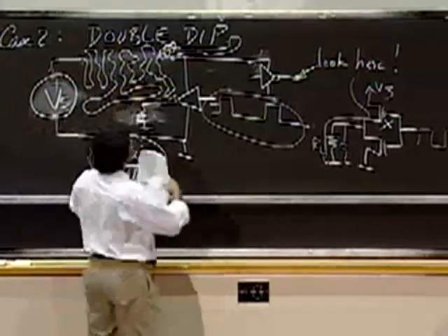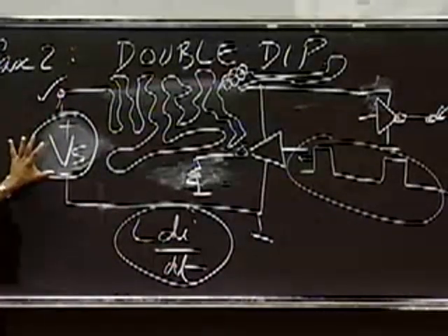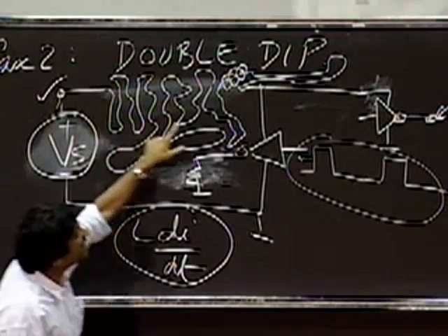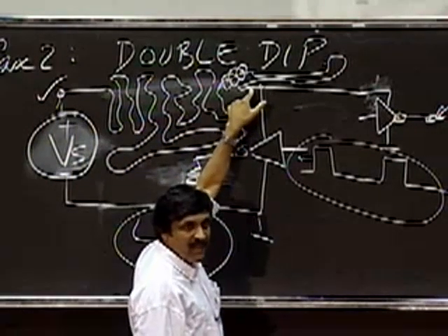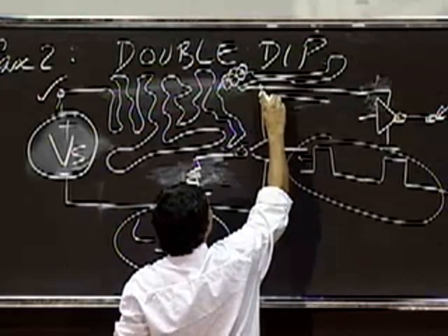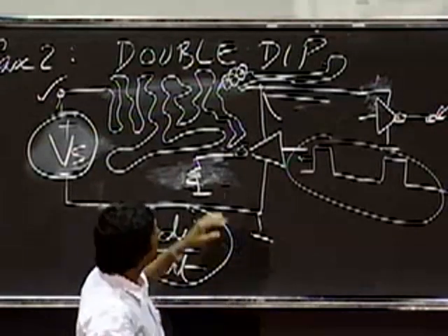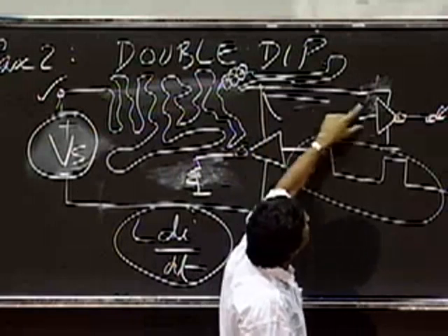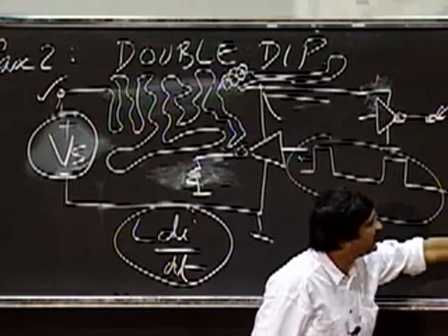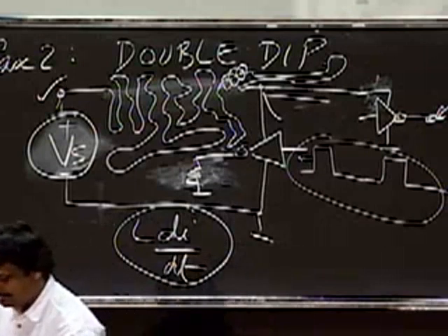In other words, the power supply here is fine. While you guys are watching, I switched in a huge Mongo power supply. And so this voltage is fine. But then this voltage after the wire is the problem. So this voltage here doesn't look like this anymore. Rather, it has spikes that go down, for example, and when I switch the other way, they go up. So what I end up having here is big spikes on this power supply, and when this guy's power supply goes wacko, then I see the spikes on its output as well. Okay, so what are the solutions to that?